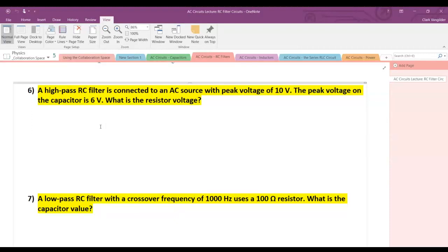So current and voltage of a resistor are always in phase. So again, I'm asking you to remember what you read and or watched in lecture. In resistors, voltage and current are in phase with one another, but capacitor current leads capacitor voltage by 90 degrees, pi over 2. And so, you have capacitors, inductors, and voltage will lead current in one and the opposite in the other. Those are some basic pieces of knowledge.